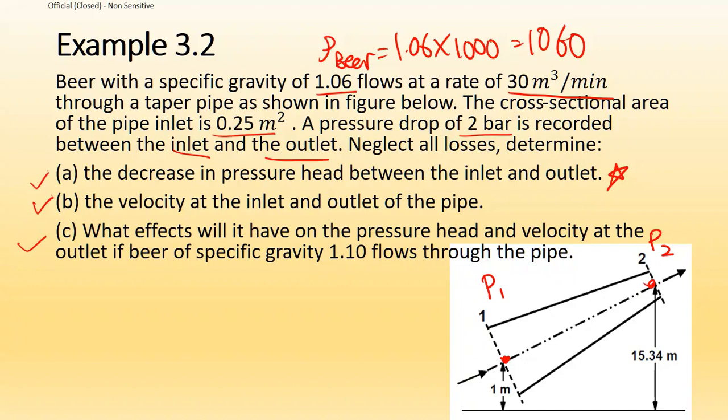We can still measure total head, but with a special device. But if I put an open manometer at this point and an open manometer at this point, it's going to give me just the static head, P1 or H1 or H2. This is the static head. So don't be too afraid of the term total head. Total head cannot be measured at this point yet.